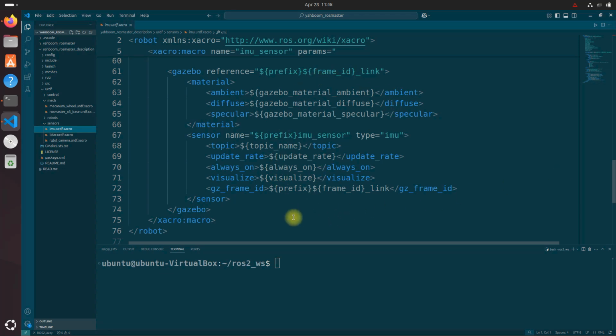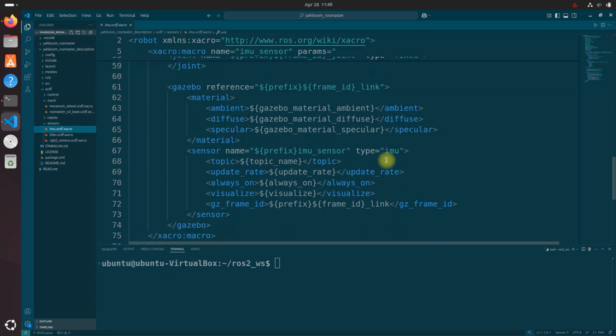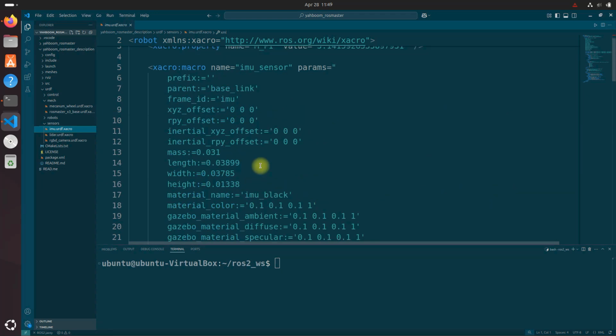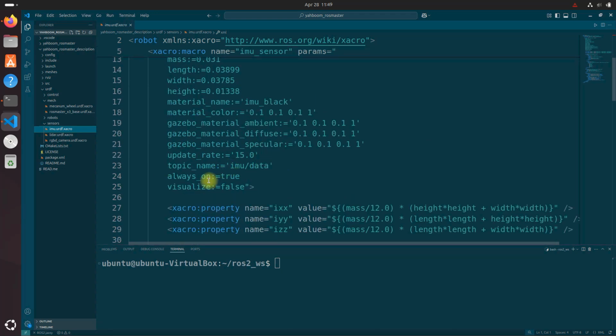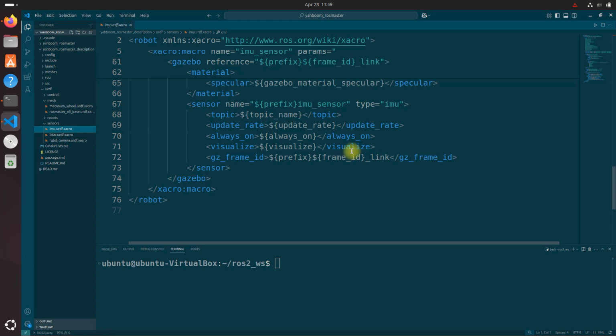So what does this mean? Okay, what does all of this gobbledygook mean in the Gazebo reference? Well, you're creating a virtual IMU sensor that publishes its data to a ROS topic called imu_data. And where do we get the topic name? That funnels in from here. You can change it to whatever you want, but I like to keep it imu_data. And the visualization of the IMU data is turned off by default, since typically you don't need to see sensor data graphics like the IMU during simulation.